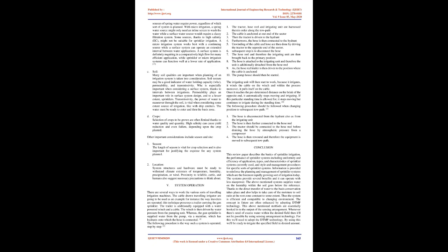4. Irrigation system planning and design considerations. Proper system planning and design is important to irrigation water management, IWM, and requires the thoughtful consideration of many elements. Selecting a system must include the following major items: management, water, soil, and crops. A. Management. The irrigator and planner need to collaborate in order to develop the best plan. The discussion of desired system type must include an understanding of management, operation, and maintenance requirements.